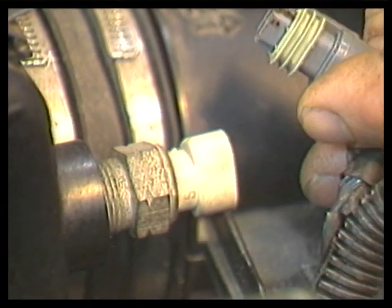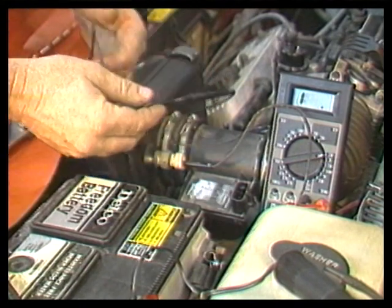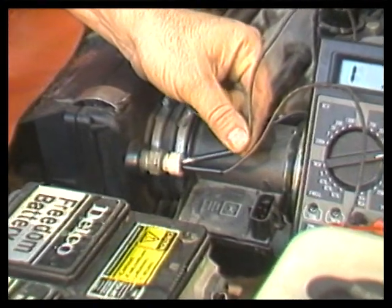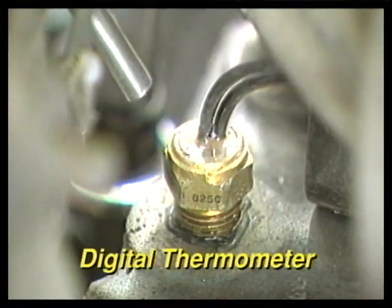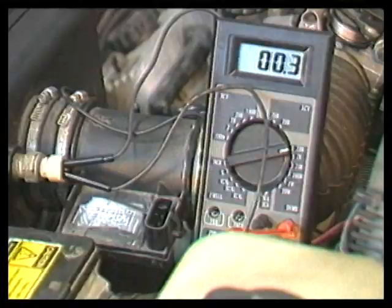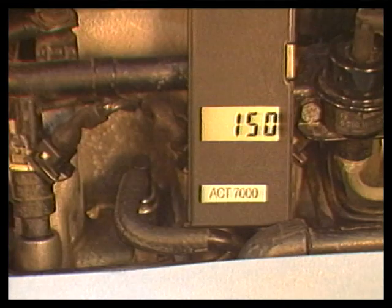You might first measure the resistance of the sensor and compare it to specs for its temperature. Here, we are using special test adapters that will slide over and not damage the sensor terminals. Use a digital thermometer to measure the actual temperature of the device. Then, compare sensor resistance and sensor temperature to service manual specs to determine if the sensor is faulty.